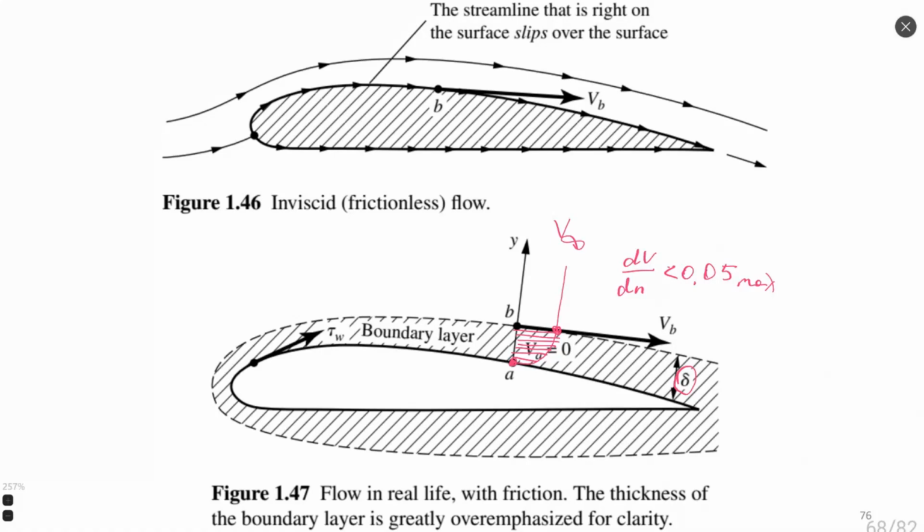I will probably add here that viscosity is a function of temperature. Since we have heat transfer between body and flow, we have redistribution of energy. It becomes very important because it impacts not just thermal processes by itself, but also viscosity.